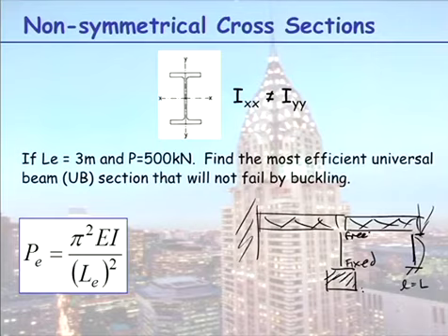And some people go, oh, but the bridge is supporting the column. No, the bridge is loading the column. The bridge, can you see, it can still move a little bit sideways. And if you have that little bit of movement, you have to conservatively assume it's free. So in this case here, you would say your effective length is equal to twice your length. So be aware of that.